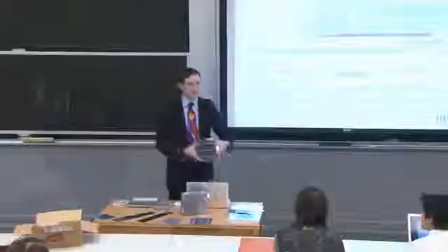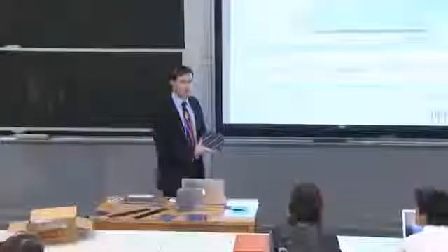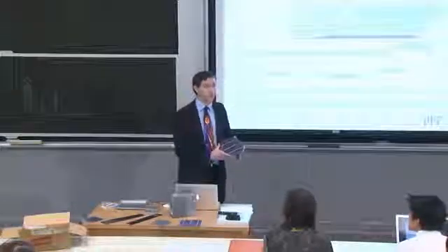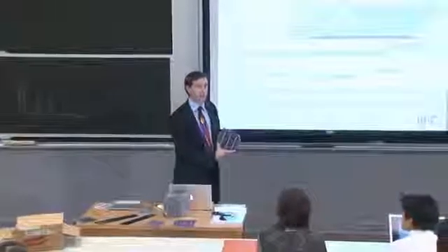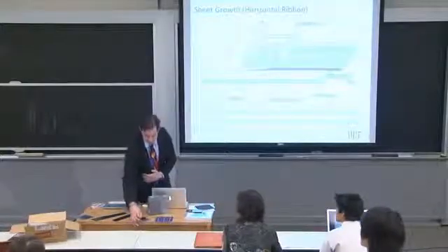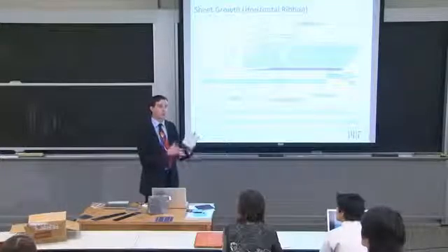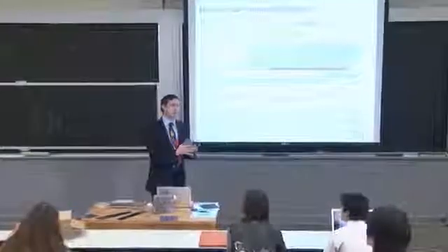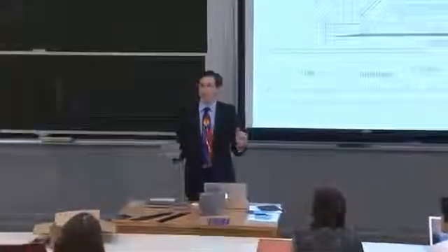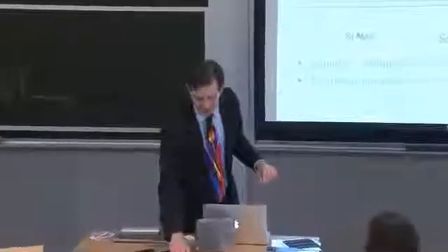Okay. So that's the standard diameter, or let's say linear dimension, usually a rectilinear shape, a square. And the multicrystalline silicon ingot material is typically of this size as well. And you can already see that these wafers that I have up here are a bit small. These were the previous generation size. I believe these are 12.5 by 12.5 centimeter squared. Most laboratory devices that you and your colleagues will manufacture are on the order of 1 by 1 centimeter or smaller because of a variety of factors.